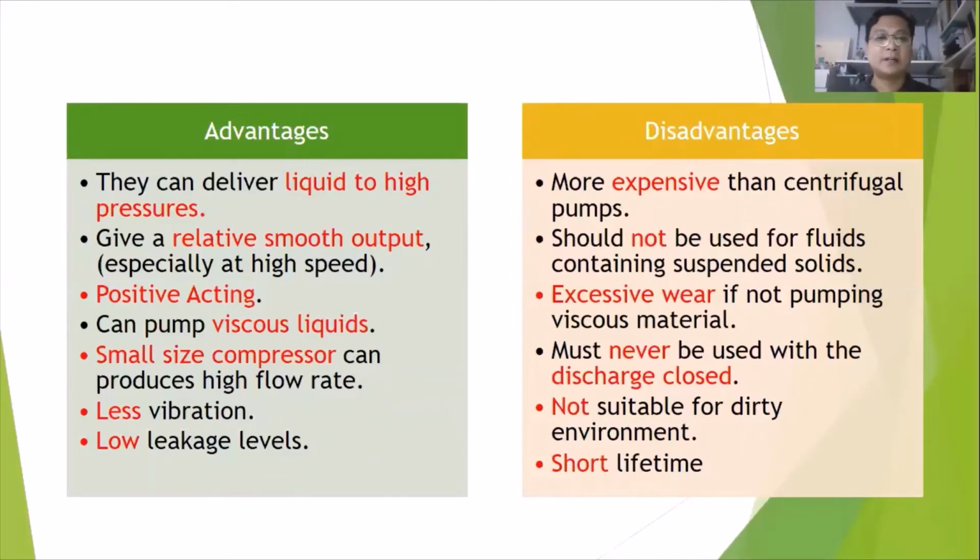But it also has a lot of disadvantages: more expensive, should not be used for fluid containing suspended solids, excessive wear if not pumping viscous material, so it should be used with viscous material. If not, it will give high wear inside of the pump. Must never be used with the discharge closed, not suitable for dirty environments, and short lifetime, very short lifetime.